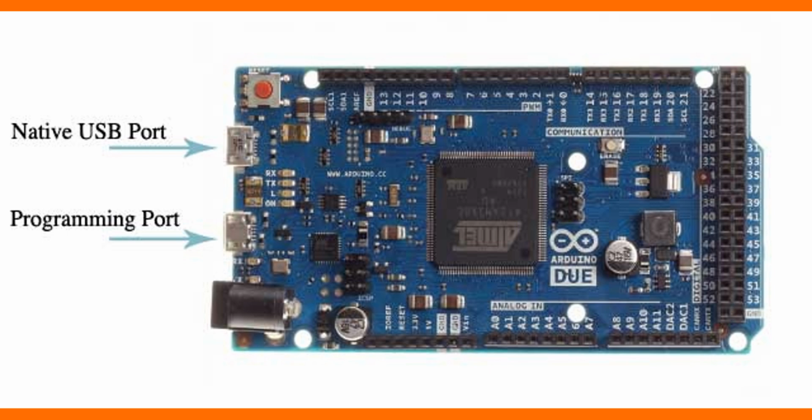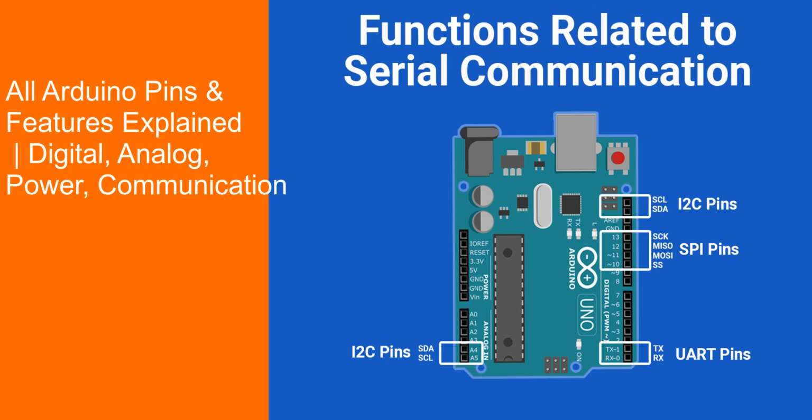All Arduino boards support communication interfaces. UART or serial uses RX and TX pins to communicate with computers or other devices. Some boards like the Mega offer multiple UART ports.